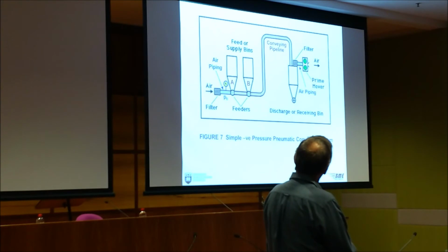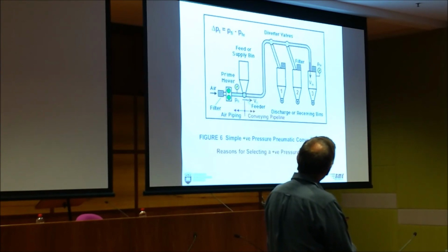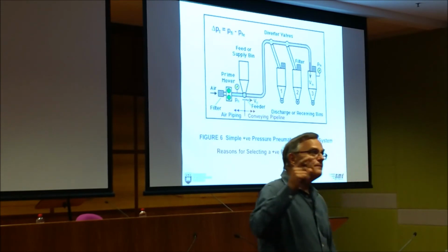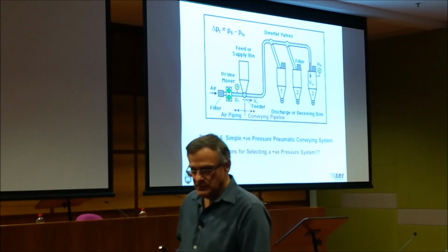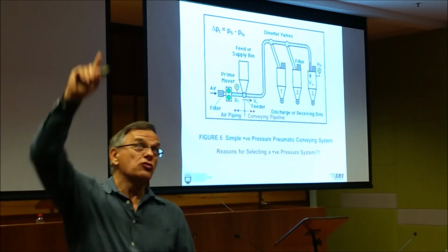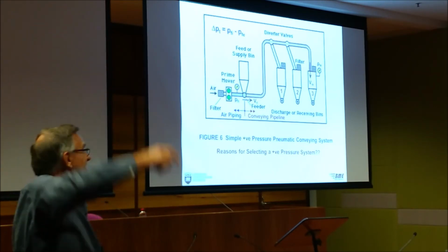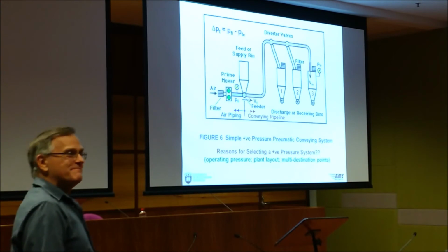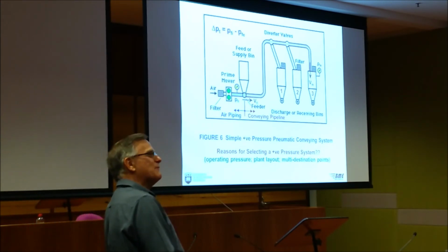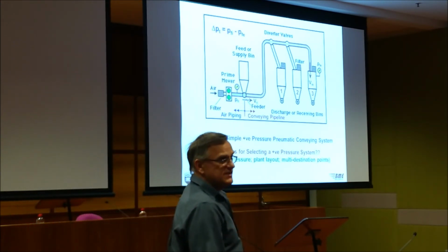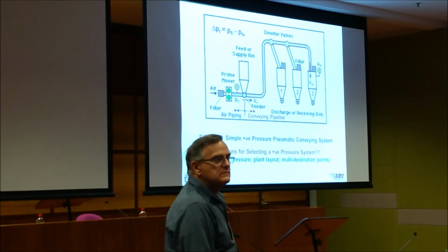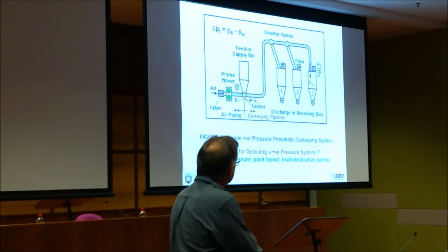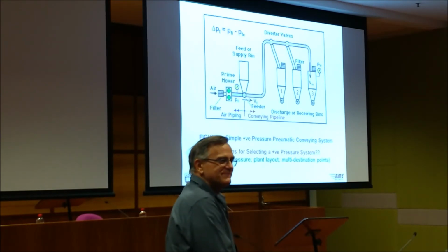Yep. And in the last system, this is the bend that will wear out first. Remember that: the last bend will wear out first. That bend usually is on the top of the bin, on the silo, up in the air, and you can't get to it. It's the first bend that will wear out, because the velocity there is the maximum. This bend will be the last to wear out, because that's the first bend in the system.